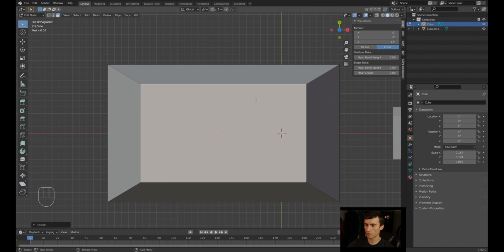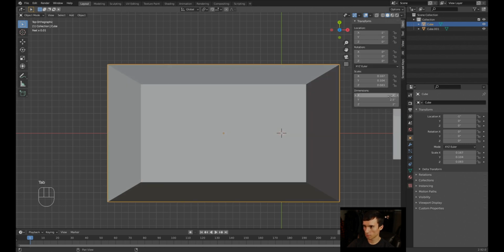Of course I could do the mathematical calculation. What percentage of, you know, what's my width? 2.5 would fit the 0.95 width, or maybe like 1.2 width, so we have thick walls. I'm gonna guess it. And this will allow me to use the measure tool to measure the width. That's 1.7, so it needs to be a little bit smaller. I'm going to delete that measurement